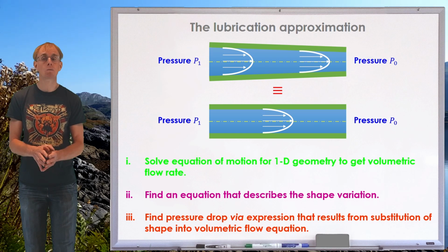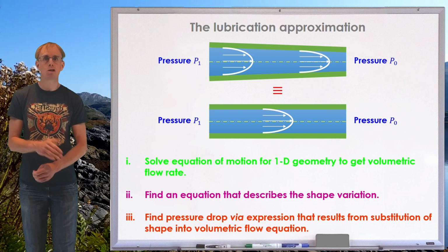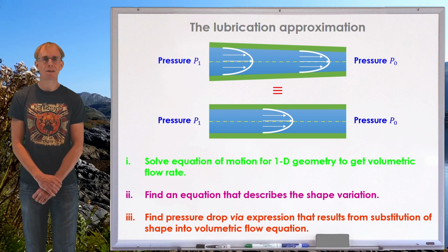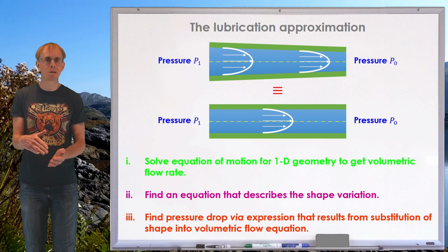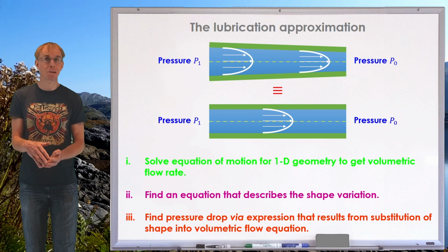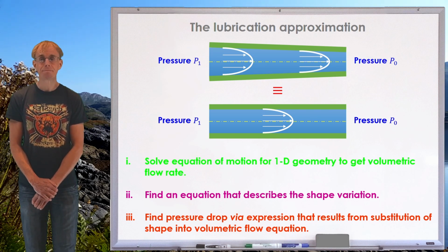So you'll see right away there's going to be a limitation on this method as to exactly how much this tube tapers as a function of length. If it's tapering a great deal, then this may not be a very accurate way of estimating pressure drop. But if it's only tapering slightly, then it may well be fit for purpose.